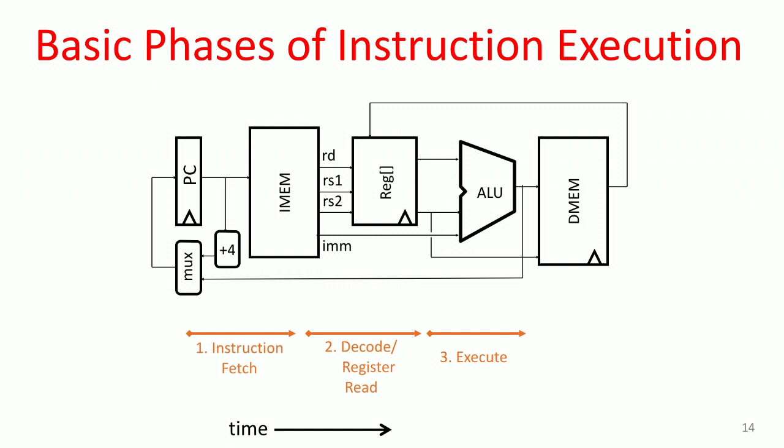Usually the ALU is used. It's not used for all instructions, but for most of them. And that's called the execute phase, because these operands come into the ALU, and it can do what it needs to do. This is, again, just a combinational logic block. It might add those two values, or it might subtract, depending on what the instruction's doing. The result will come out of the output of the ALU after some delay. And if this is an instruction that uses the memory, like a store instruction, then we'll get the result ready to go into the memory at the end of the clock cycle.